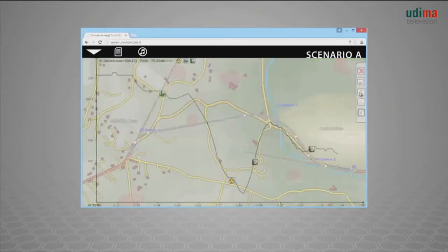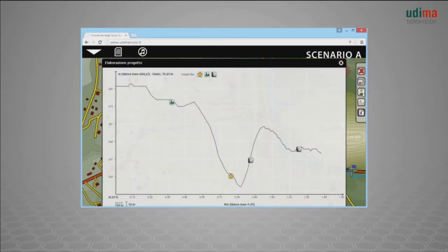The following step consists in the analysis of the longitudinal profile to study how the road is developed from an altimetric point of view. The application can elaborate a longitudinal profile of the road. The protected areas are visible and you will need to decide how to tackle these constraints. In the design, it is possible to read the amounts of each single point. On the longitudinal land profile, we should track the longitudinal profile of the road. In this stage, we must consider the slopes in order to guarantee the traveling speed safely.